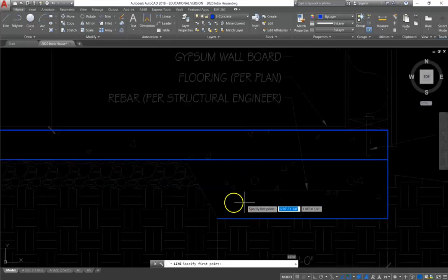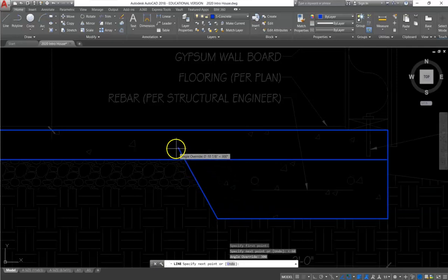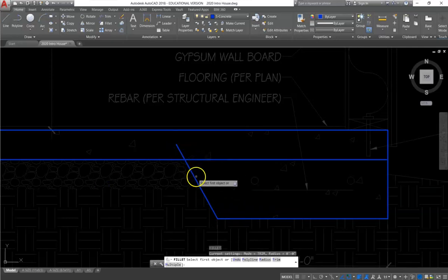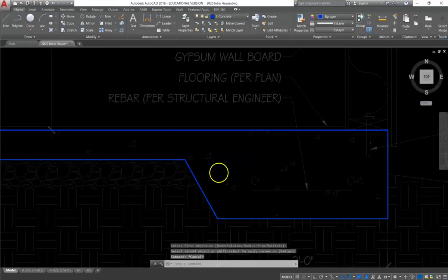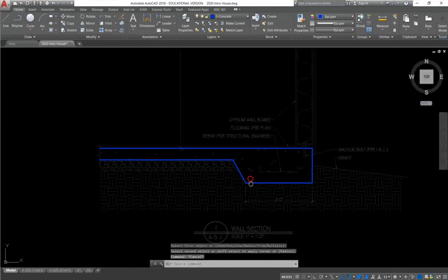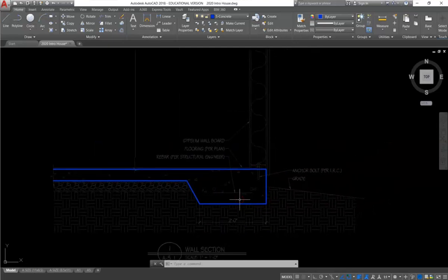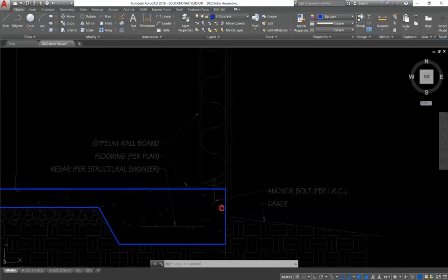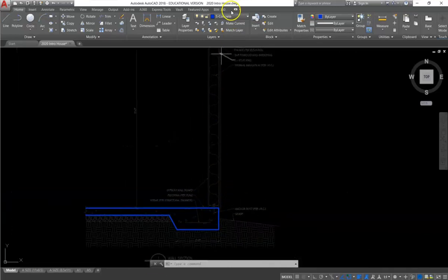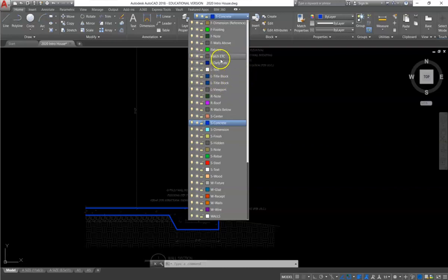Okay, in our drawing, we have an angle of 60 degrees, and then we will fillet this corner. So for our concrete, we have our 4-inch slab, which is throughout the home. Then we have our turned down footing on the exterior walls. Alright, so moving forward, we begin drawing our exterior wall. So we will draw the wall with our wood layer.